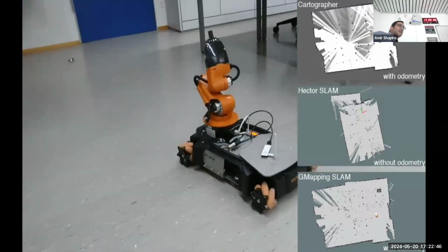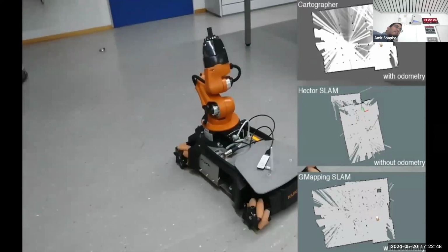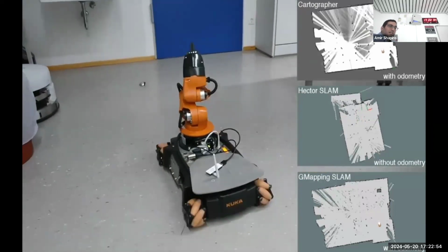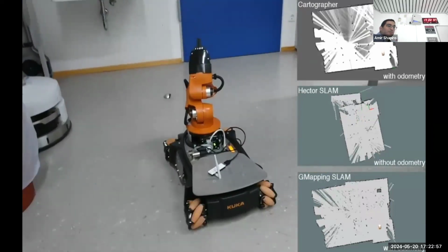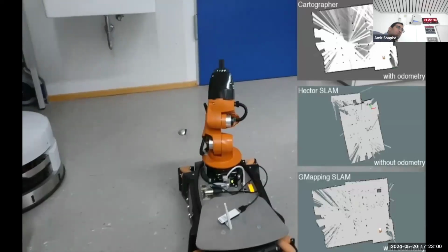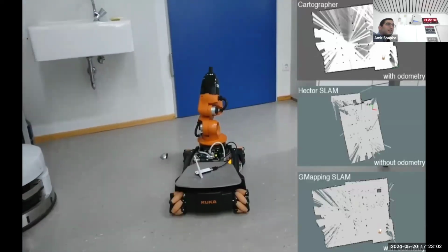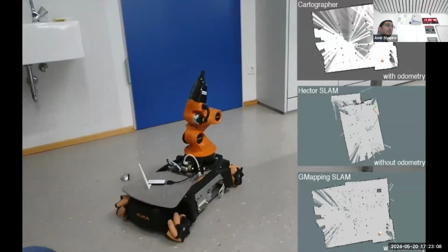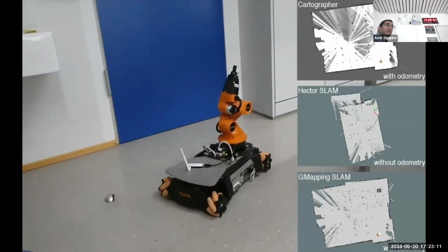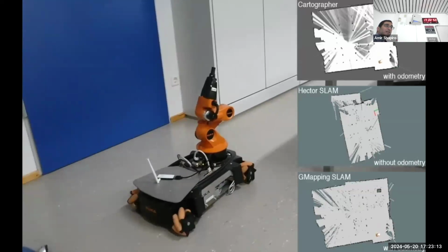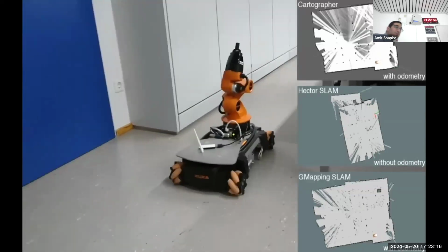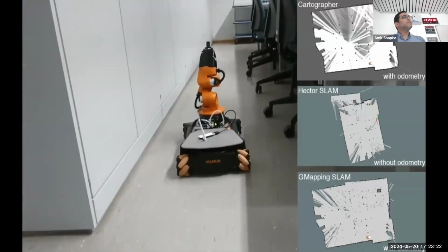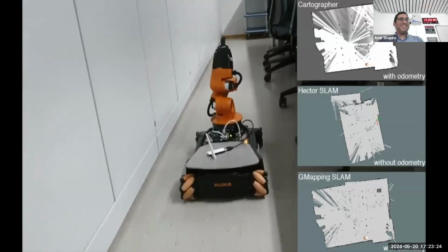Does the robot collide with things, or does it know the distance? It knows the distance to obstacles because it has LiDAR, and therefore it computes its motion in order not to hit an obstacle. And this is exactly what the Cartographer is doing. It has the local planning that plans the motion locally and avoids the obstacles. So it has the global planner and the local planner, the same thing that every robot should have.